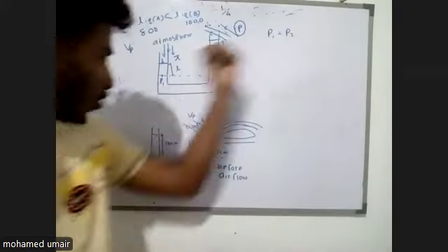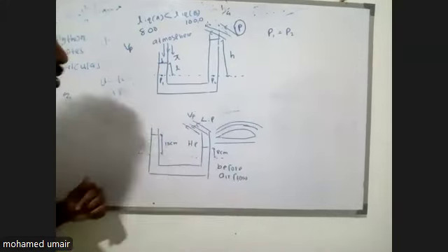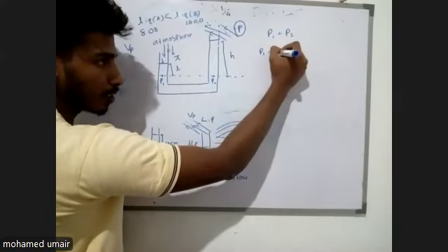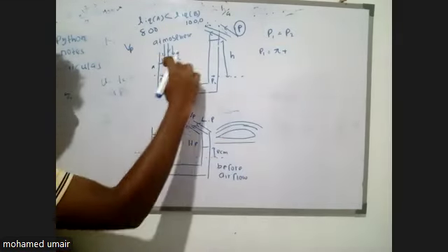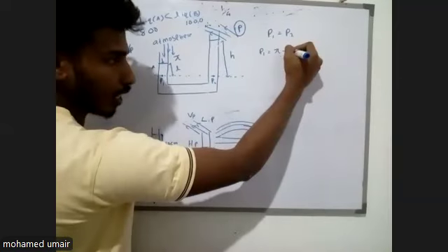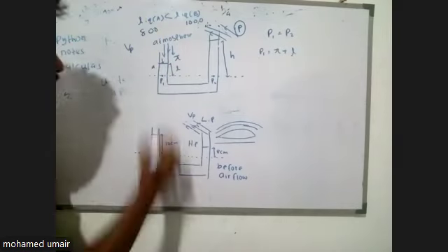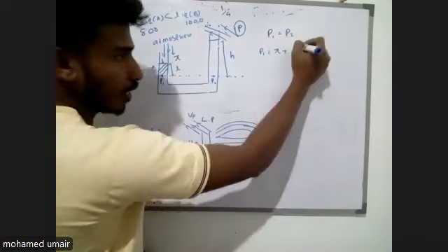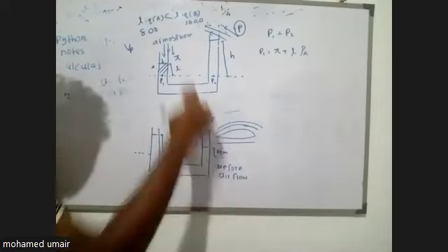Now let's write the equation for P1 pressure and P2 pressure. So P1 is equal to the atmospheric pressure plus the length of liquid A, which is L. The density of liquid A, I'll just take with parameters, rho A. I just write the U-tube equation, h rho g.